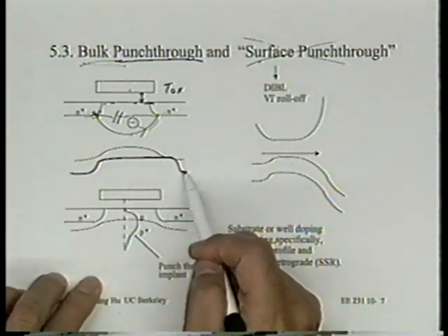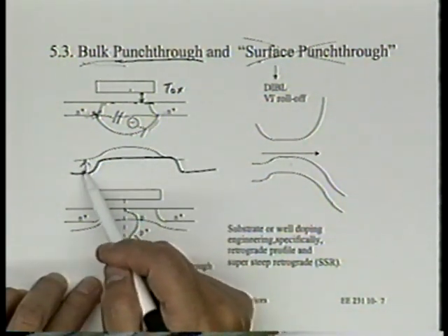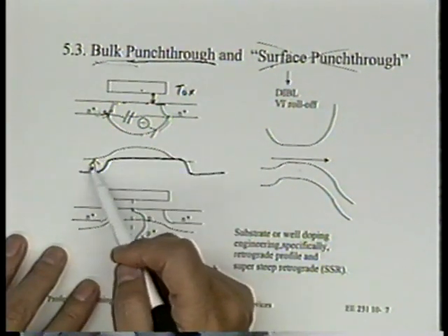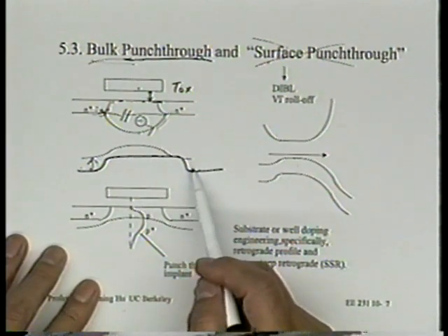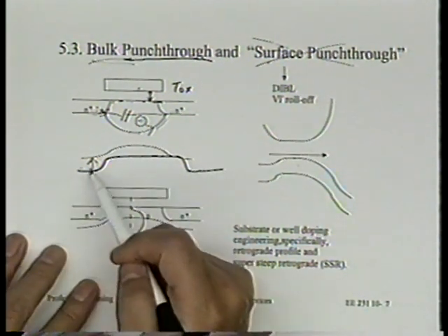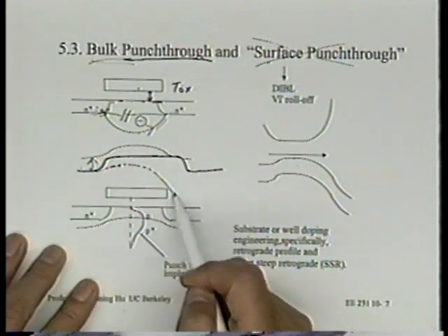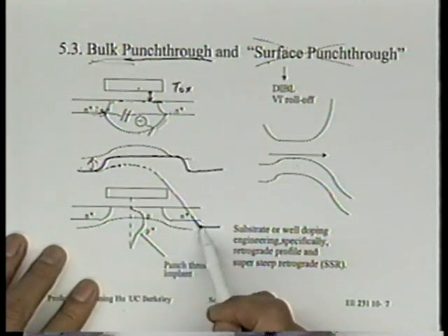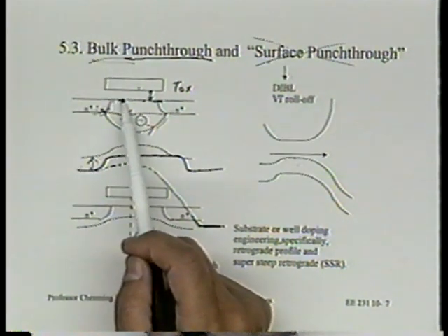All right. So with 0 VD, this is my barrier. It's very good, right? Because it's a barrier, electrons cannot flow from the source to the drain. Now I start to apply a drain voltage. Can you see that it might look like this? Do you see that? Same thing we talked about last time, right? Except this will happen at a lower VD than what causes the barrier to lower near the source.